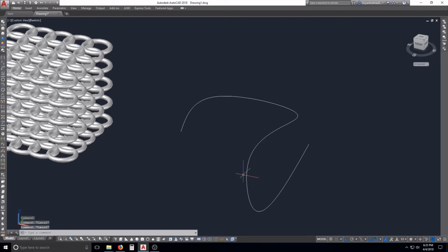So what we're going to do, and you can do it with any shape, you can say, let's use a polygon, P-O-L, polygon there. Basically, a polygon is like the pentagon, or a hex head bolt, or whatever. Or a square. A square is a polygon if you identify it as having 4 sides. Where it's asking for sides here, if you said 4, you'd get a square. But with more sides, it's going to look neater on here. So let's just go with 7 sides.